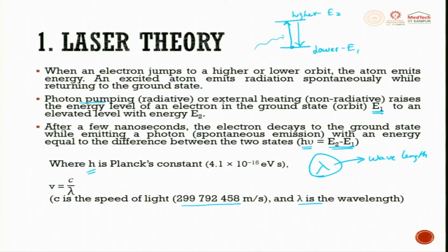Why do I buy a green laser? When you try to buy an additive manufacturing machine, the vendor says, this machine is wonderful because it has a green laser. What is the big deal of a green laser? It is lambda. This lambda in turn relates to the photon, and this photon is an energy which helps you in melting. So, this lambda is very important.